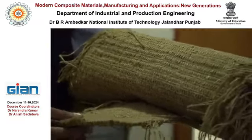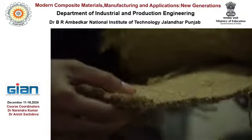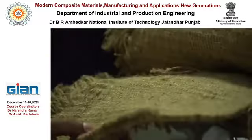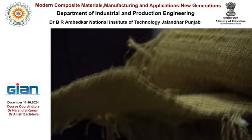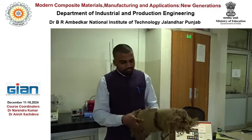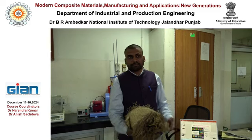So in this particular structure, let's say it is for example 8 or 9 mm thickness, and to produce this much thickness with a laminate, I need to use multiple layers of this material. But if you look at this, since this is the integrally woven structure, the failure modes will be different. It will take a maximum load compared to your laminate, and since the failure mode is different, the life of the composite material in this case will be more than your laminated composite.